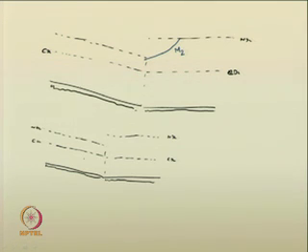So, in this case one can imagine, say from here partially the water surface profile changes like this, and partially it becomes M1 here and partially it becomes M2 here in channel 2, like that. You can visualize these things. So, whether this is also theoretically possible or not, you have to think for yourself. We will discuss that further.